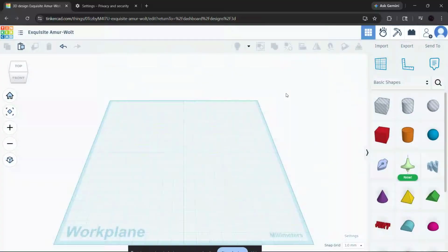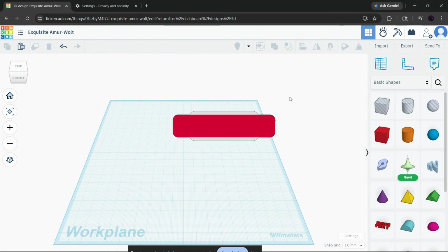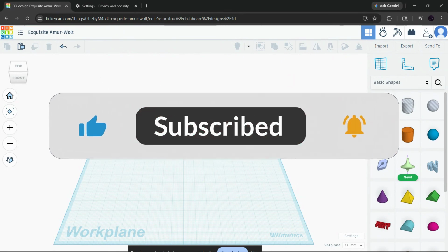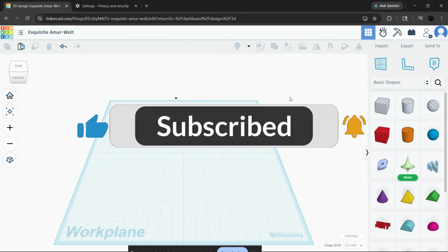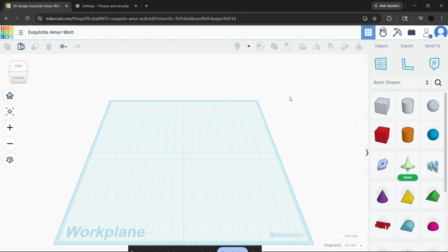If you're seeing the Tinkercad Error Processing File message, don't worry. In this video, I'm going to show you exactly why it happens and how to fix it step by step. This issue usually means Tinkercad can't properly read the file you uploaded, and that can happen for a few different reasons. The file may be too complex, the mesh may be broken, the browser may be causing problems, or the import settings may need adjusting. The good news is that most of these fixes are quick and easy, and you can usually get your file importing again without starting over.